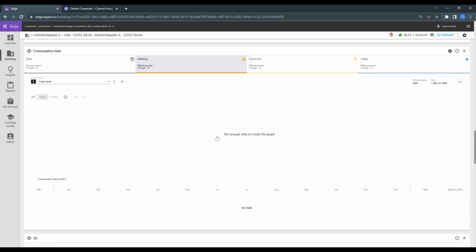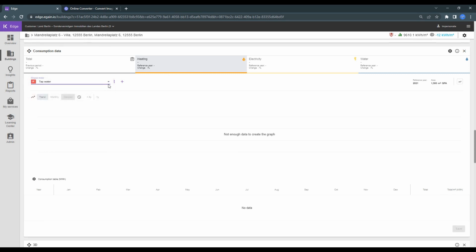Now, let's take a look at how you can start to set up the meter logic when adding energy statistics. To simplify that, Edge presents you with a preset of meters. A tap water meter, red, marked as physical meter with a P, which we will rename to heat (brackets, only baseload). And a heat meter marked with a V, which we'll rename to heat (brackets, heat only). This preset is done as most heating centrals have a centralized tap water. If you have decentralized tap water with no metering, then just delete the red meter.